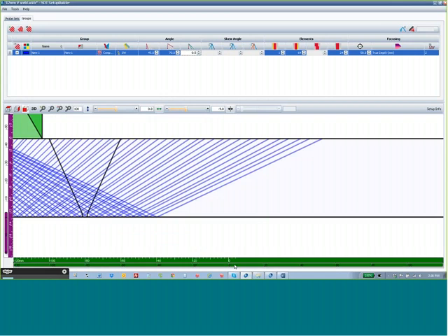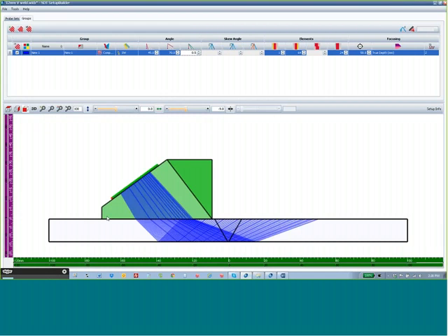It's relative to our scanner speed and file size as well. And at 0.5, from a 45 to 70, gives us a very good angular coverage or resolution on the weld bevel and throughout the weld. We'll select a focal distance appropriate for the thickness and aperture. And at this point, our compound S-scan is programmed.